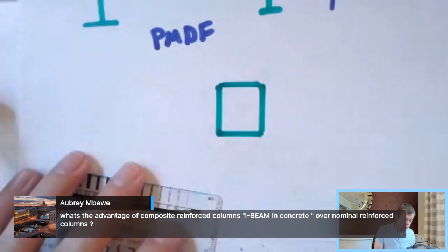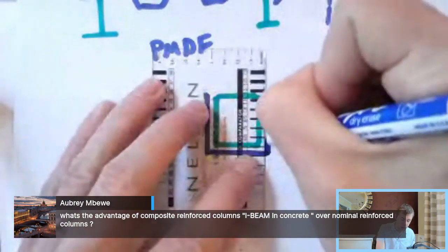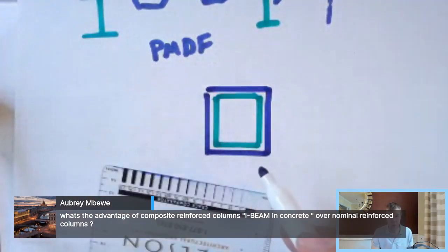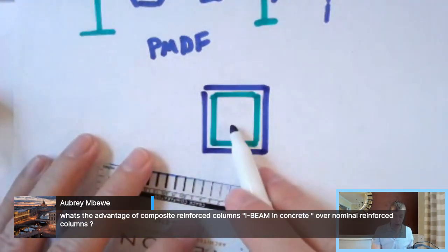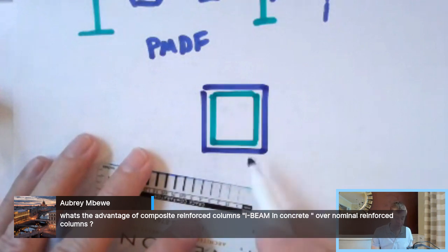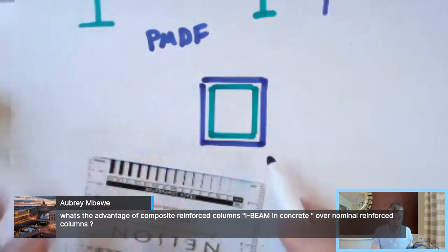Now in these systems, sometimes you can actually put steel around them, so you can actually cast them in steel tubes. Is that what you're talking about? That's what I think of as composite columns, concrete cast inside some kind of steel tube. But why would you do something like this? You would cast concrete on the inside of a steel tube to keep it from buckling. That's one big reason. And the steel on the outside helps provide strength for your concrete. That's a great reason. There's lots and lots of benefits to this.